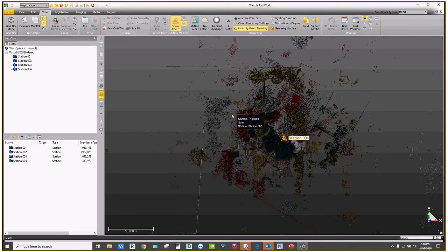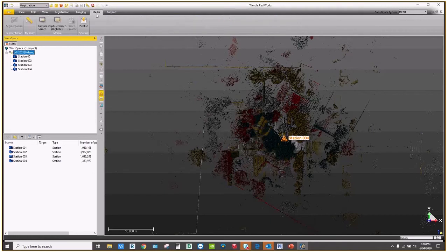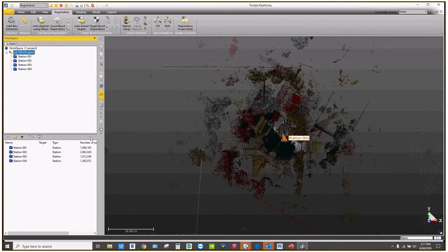So there are a few things we have to do here. We have to bring this data together, register it, and then we need to georeference the data and get it on our datum, which in this case was MGA. So firstly, to register the data. As I said, I'll come back to some of these other tabs if and when we get time, but commonly a lot of these processes are also available over in production mode, and we might deal with that in the next presentation. But most of the stuff that we're going to be doing in this configuration is in this registration tab.